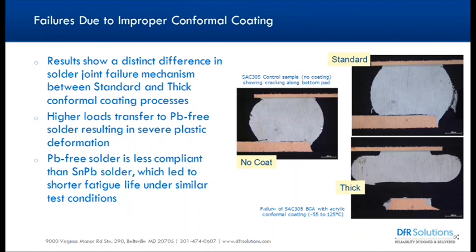You say conformal coating is not underfill. What about thin film conformal coating, like parylene? Absolutely. Yes. It is conformal coat, but it's not underfill. You can't use that. It will not help you for vibration and shock mitigation.